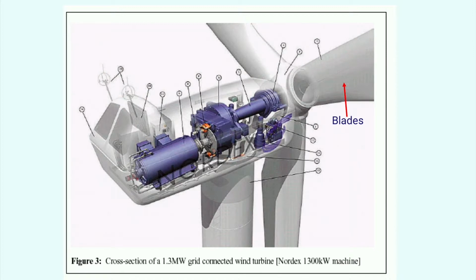The blades are subject to significant fatigue due to the ever-changing turbulent nature of the wind. Defects in construction or damage can lead to crack development or delamination of joints at the trailing edge of the blade, for example. Erosion by particulates in the air can cause pitting and loss of aerodynamic efficiency.